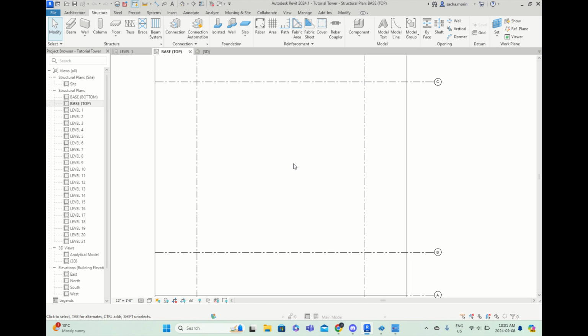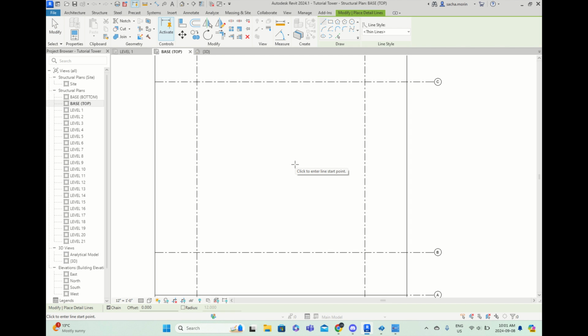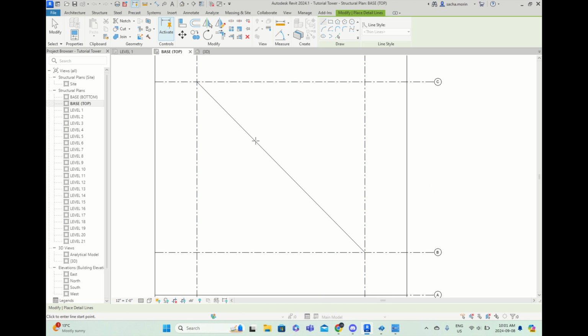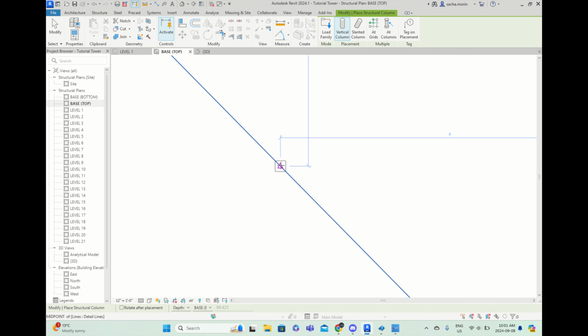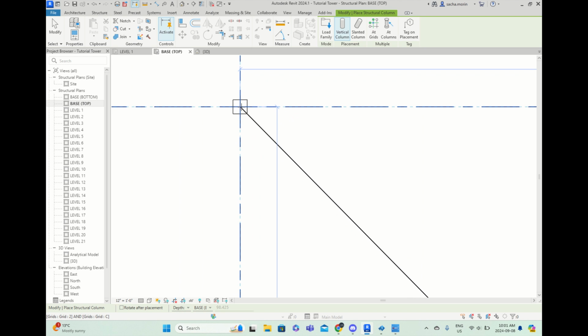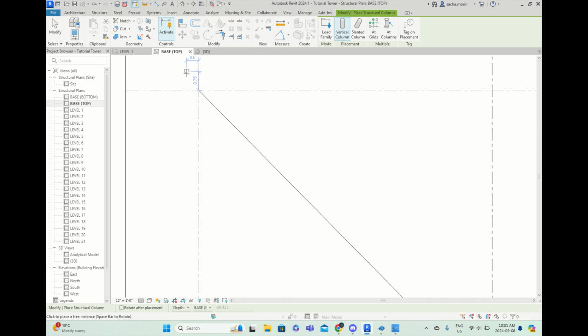And the way that you do that in Revit is that you have things called design lines. So right now, without touching my keyboard, I had pressed escape already. I'll click DL, and that'll bring me to a design line. So again, I can click into whatever corner, it'll snap, it'll make a line, and that is a design line. I can then use that to place a column on top of it. See? And again, midpoint is a triangle. The edges of something is a square or an intersection. You see it pop up briefly in pink. That's all right.